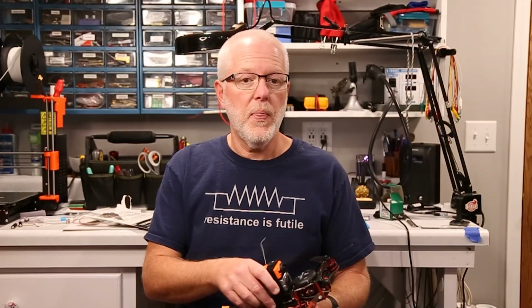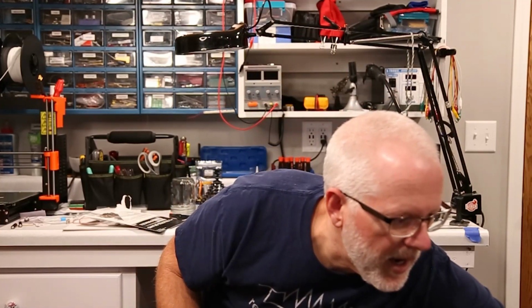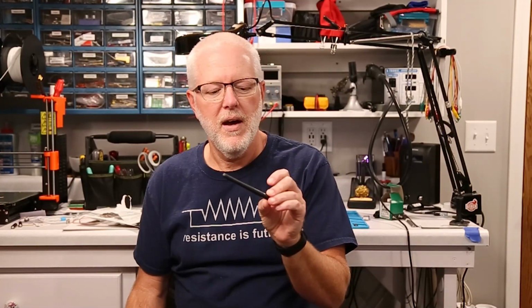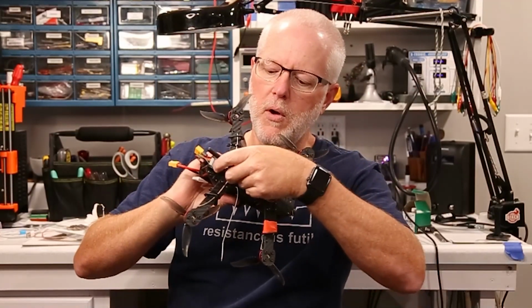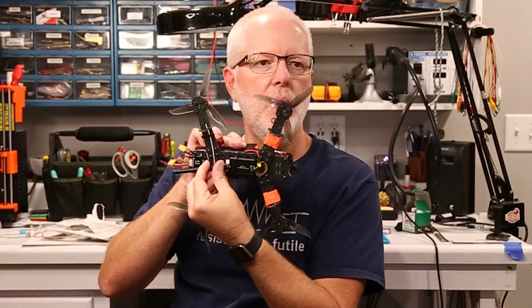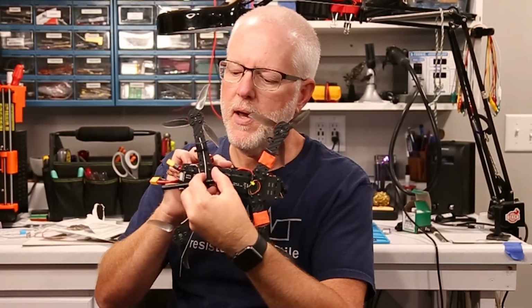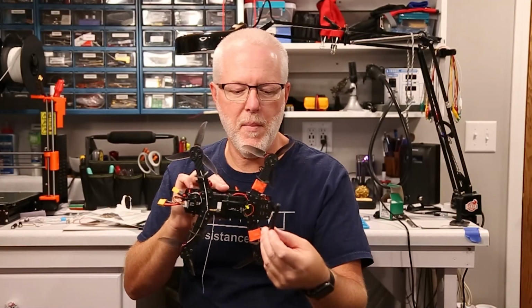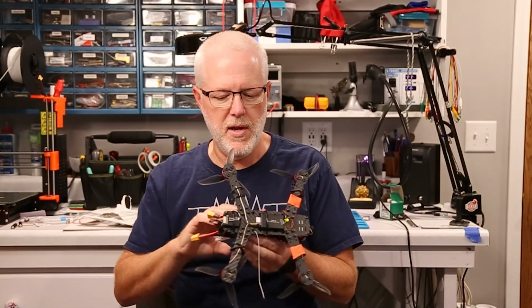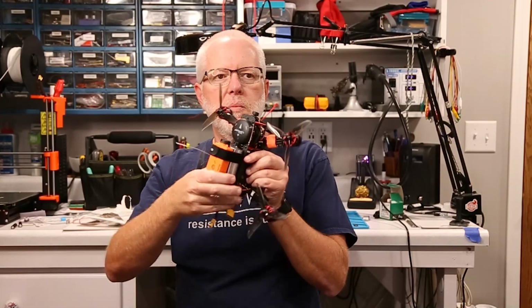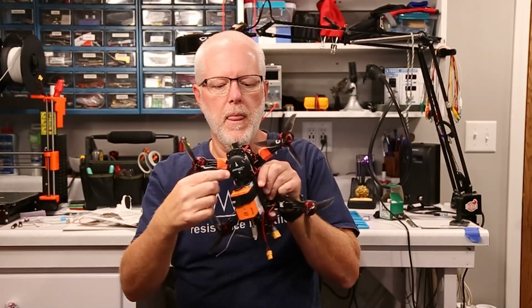So I believe the issue that I had found is this little guy. A poorly manufactured antenna from an inexpensive product. The telemetry radio is right here. This antenna screws onto the end here like so, and I believe it's a bad enough antenna that it was just allowing too much radio frequency interference to the GPS receiver, which is located here.